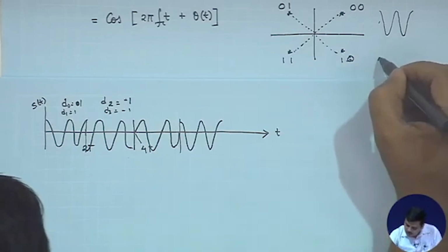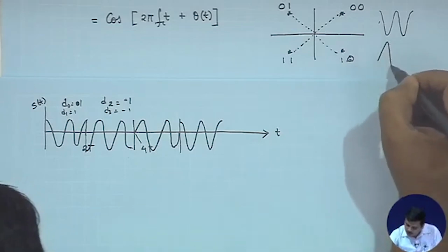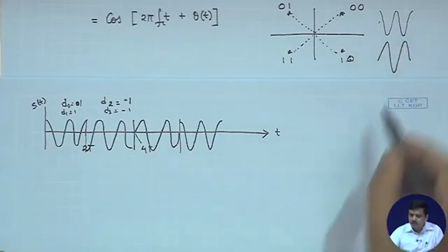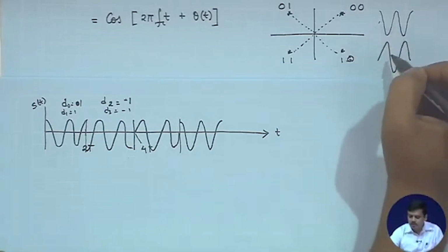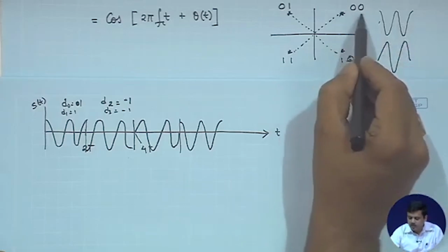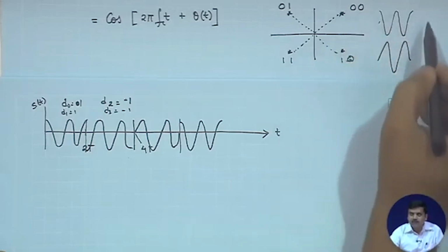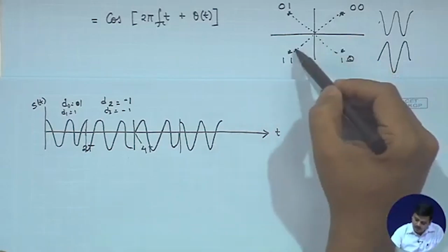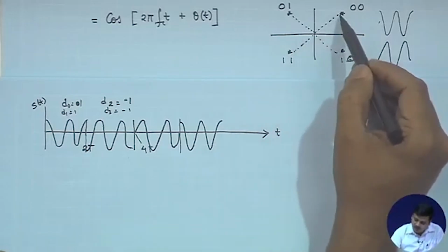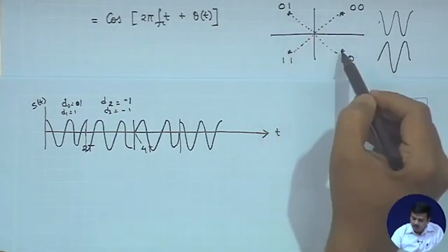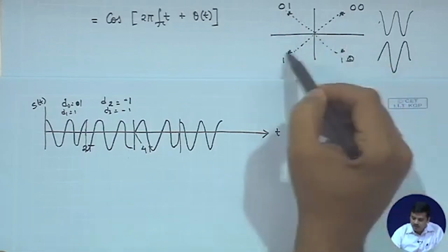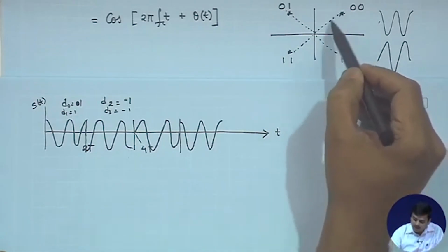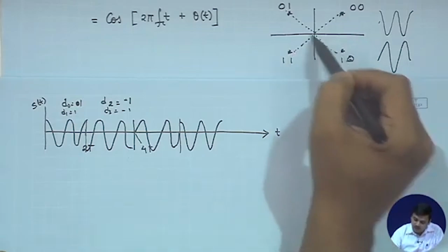So, you could get another waveform. Similarly there would be two other waveforms. So, for every two possible inputs you would choose any of the four waveforms that are available with you. So, what could happen at every 2t interval is that the phase of the carrier could change from any point to any point. What is worse is when the phase changes by 180 degree.